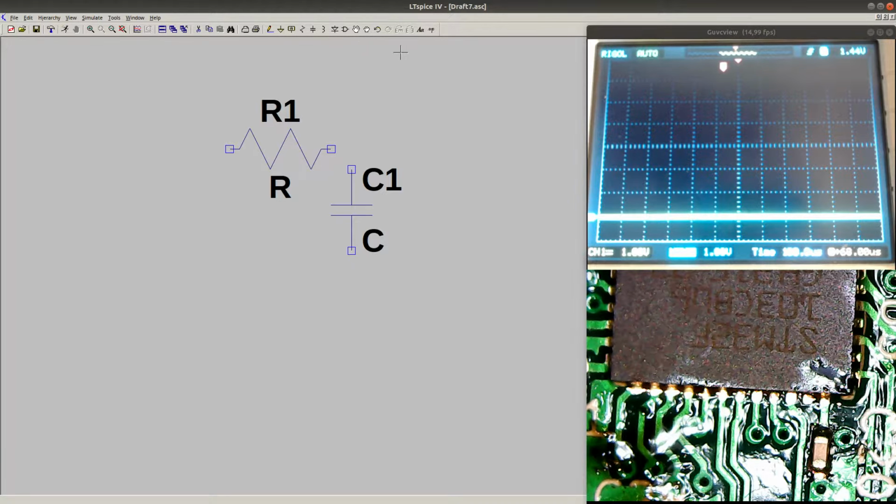So I'm going to set the function generator to generate a square wave, so that we can measure the step response of this system. And if this was a mechanical system, then the way you would measure step response is, for example, by applying torque to wheels of a machine, and then measuring how the machine behaves when you apply a step, like a square wave of the torque.